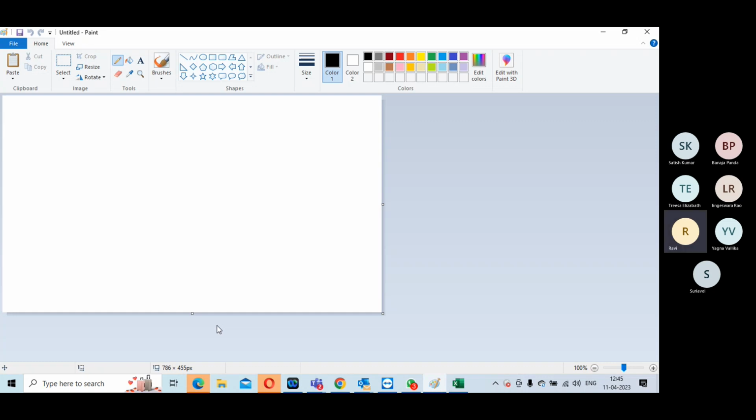Okay, now let's talk about a few things. How would you qualify a floor plan? When we match the data flow diagram, there should be a reasonably good match between the data flow diagram and your floor plan. Module placement should match roughly, congestion should be good and timing should be meetable. Then my floor plan is good.